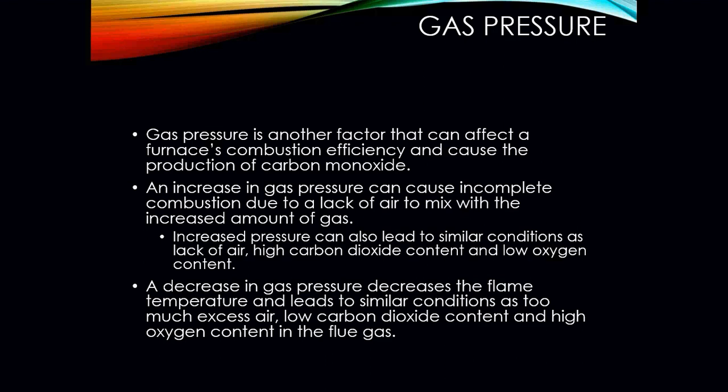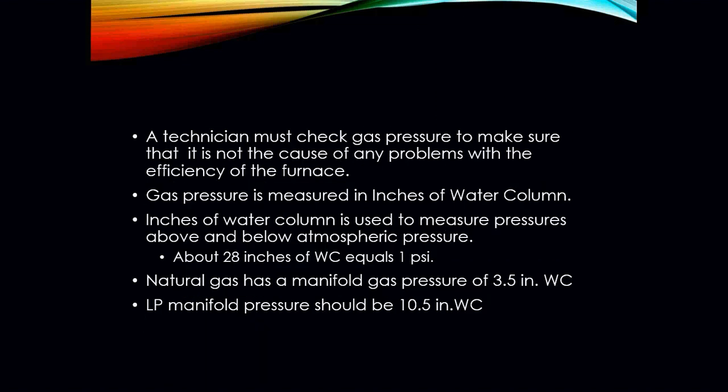So what we're really getting at here is that we have to make sure that we are giving enough air to the furnace, and that we have the proper gas pressure. All of those will coincide with each other. A technician, all the time when doing a combustion efficiency test, should be taking gas pressure measurements to make sure that it is not the cause of any problems with the efficiency of the furnace.